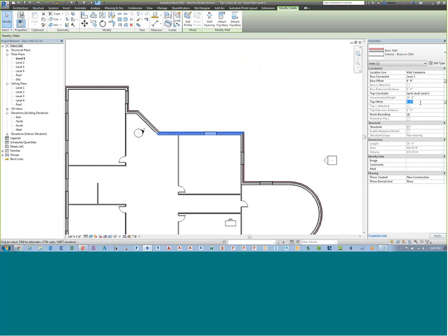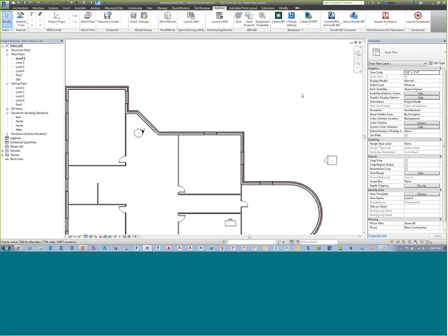They can say is equal to a certain value, say 1 foot, plus, say, 0.125 inches. Maybe I just can't remember how to do math. It will automatically do the math for me, and it'll allow me to use that in the value for the top offset. Okay.